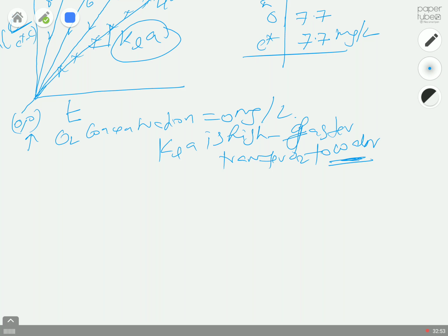If the concentration of cells is low, the whole process is not limited by oxygen, because you have more than enough oxygen dissolved in the water for those very few cells. But once the cells start to multiply, oxygen concentration plays a big role, and that's the time you have to worry about how fast you are transferring oxygen from the gas to the liquid side. I think I fairly covered this topic for this module.